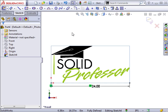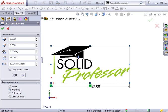If you need to edit the sketch picture, just double-click it to bring the Property Manager back up. You can select it and press the Delete key to delete it if you ever need to, too.